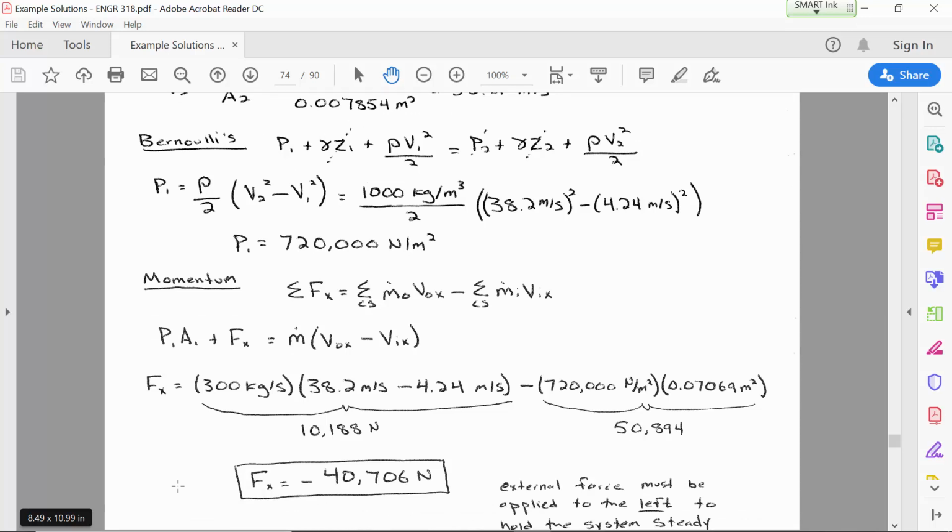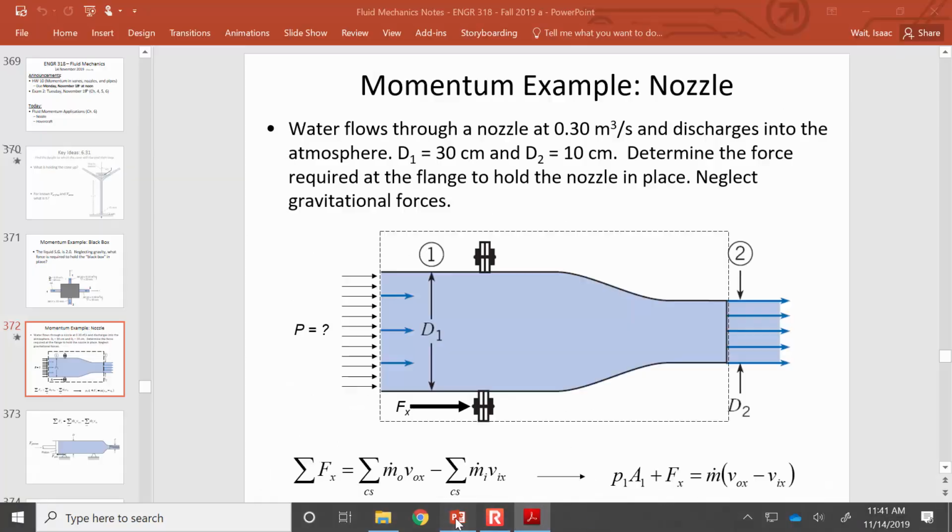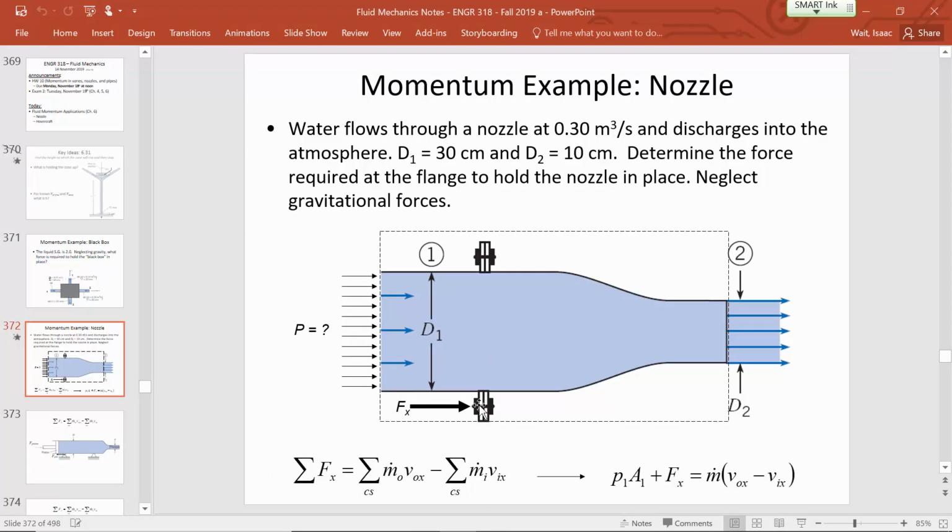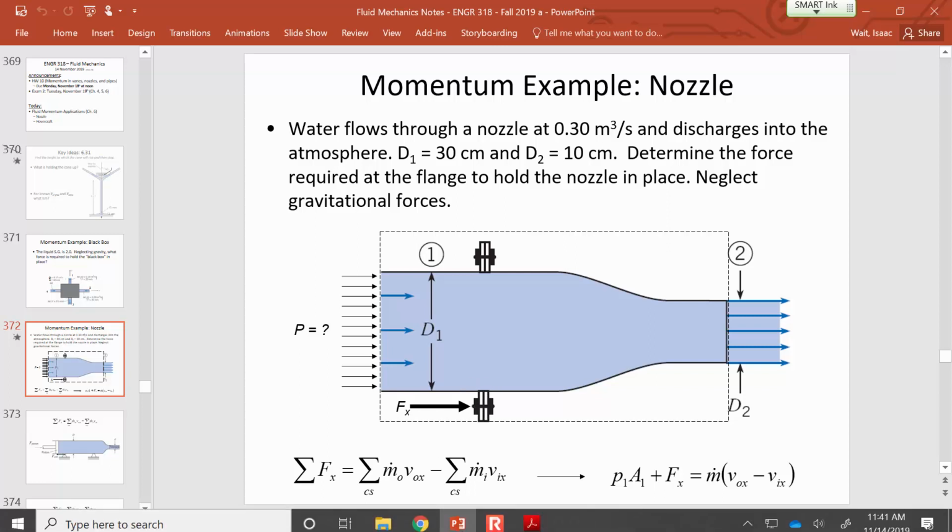So we're resisting both the acceleration of the fluid, so even just the momentum aspect of things means we're having to push to the left because of the fluid speeding up. But then that pressure thing also means that we have to resist even harder at the left. And so the force direction was just indicated to the right in the sketch here.